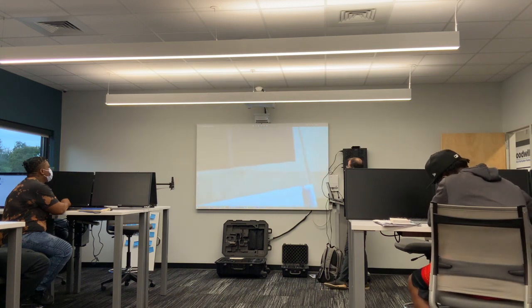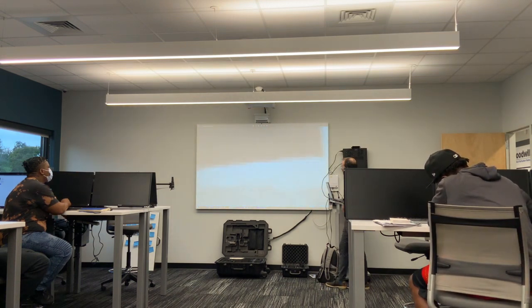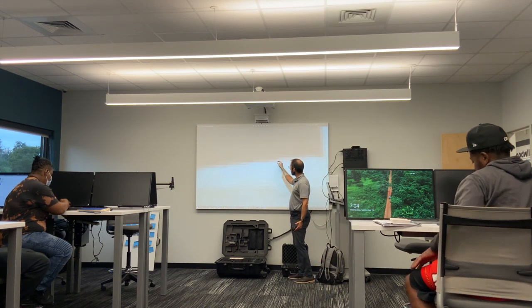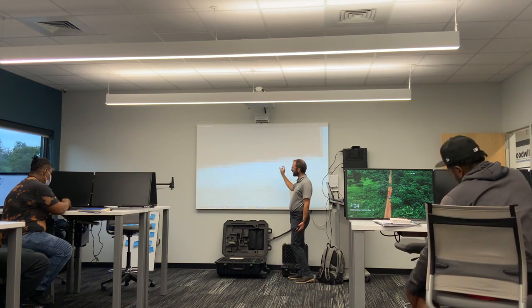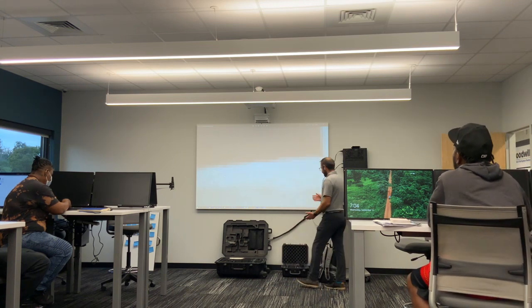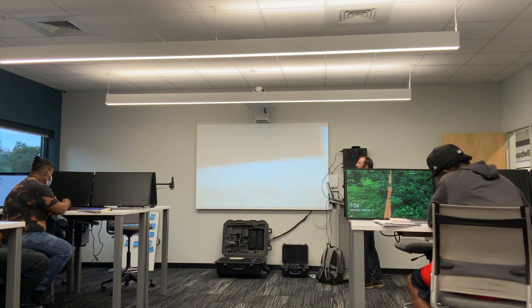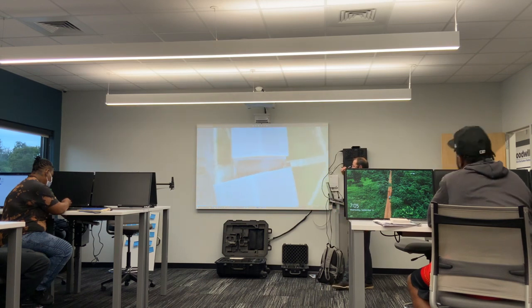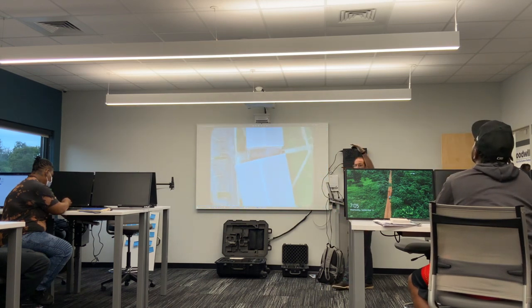So like we were saying, when we're talking about ground sampling distance, 1 pixel was about, what did we say, 1.5 centimeters. The lower that distance is, the higher quality your image is going to be. And for a payload like this, it's really going to depend mainly on your flight altitude. So the lower you are, the crisper your image is going to be.